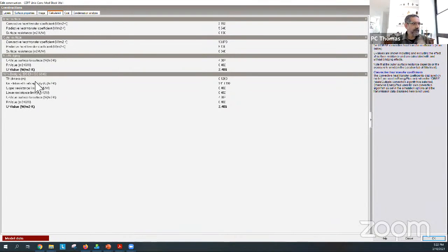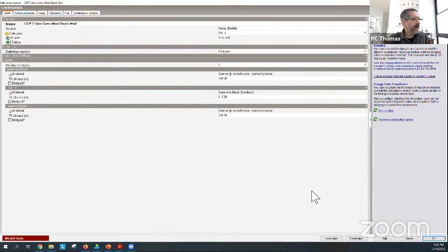So, you know, these 2.4 might actually go up to say 2.7, and then you model that. So you put the 2.7 as your no bridged value, and DesignBuilder Energy Plus will do the calculations for that. Okay. So that will give you, and behind each layer, there's a material.